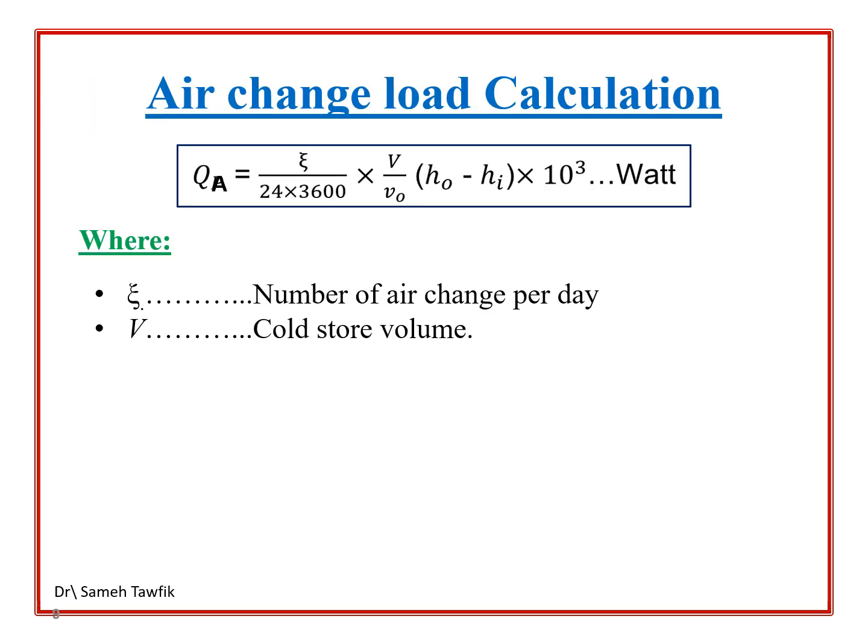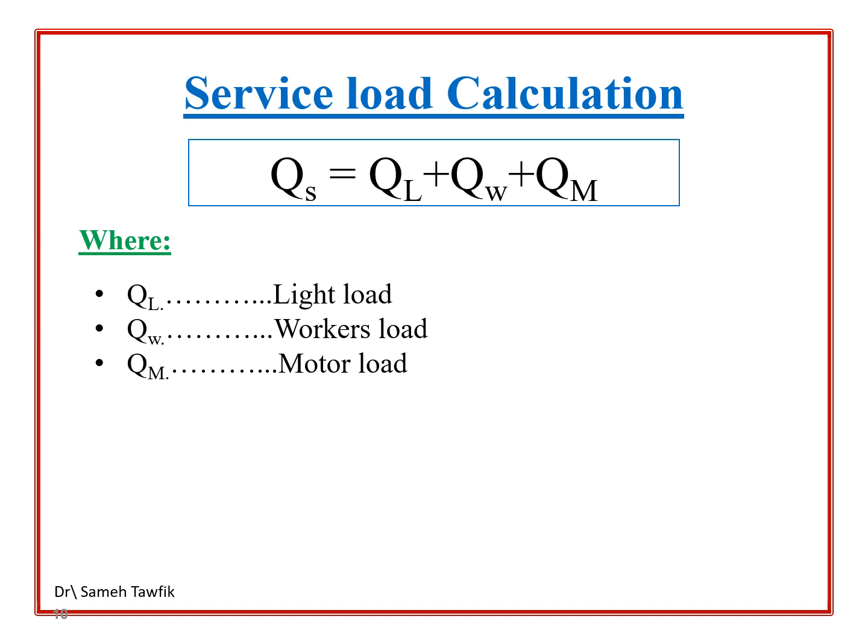Air change load calculation. Moving on to the air change load. This calculation is based on the number of air changes per day and the volume of the cold storage area. Proper ventilation is essential for maintaining product quality, and this calculation ensures that the system can handle the required air exchange effectively.